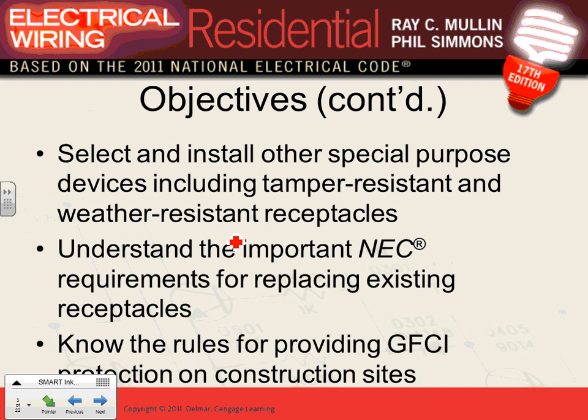Also, since we're talking about dwellings, I want to draw your attention to the term tamper-resistant receptacle. All the receptacles in a dwelling must be tamper-resistant, and you guys have seen that. All of them, no exclusion. When I say all of them, I mean the 15 and the 20 amp at 120 volt. These are the most common receptacles. If you have a 240 volt receptacle, they don't have to be tamper-resistant.